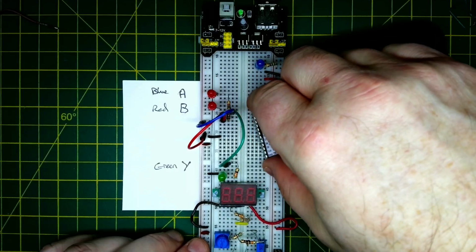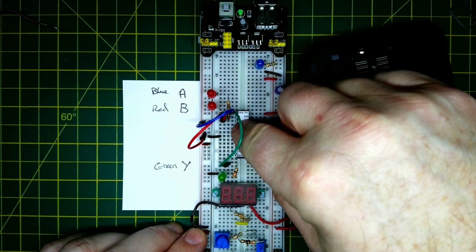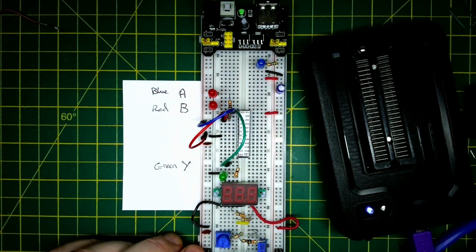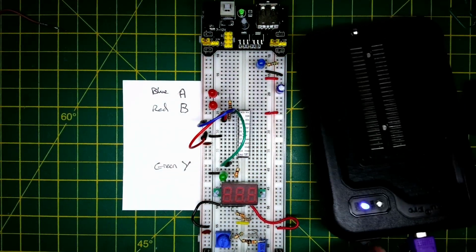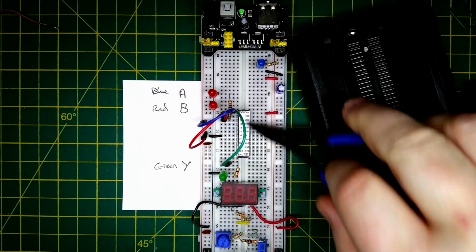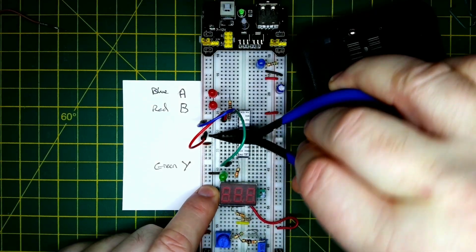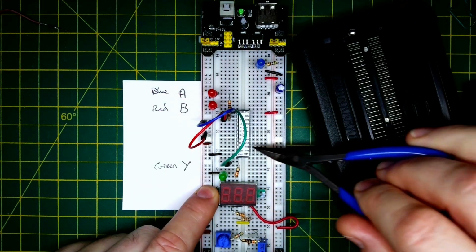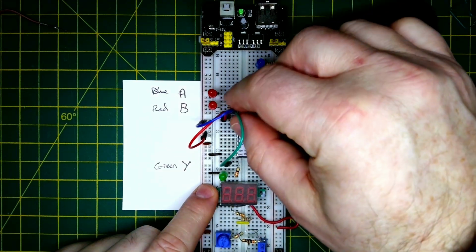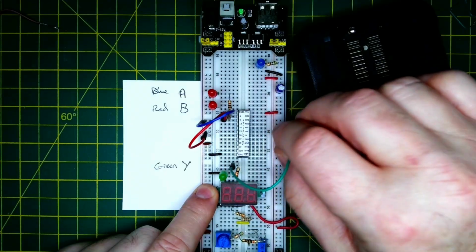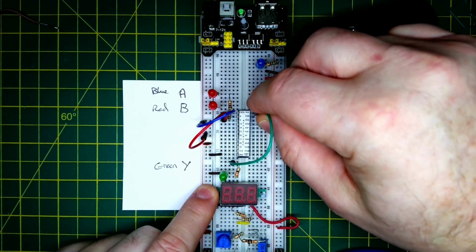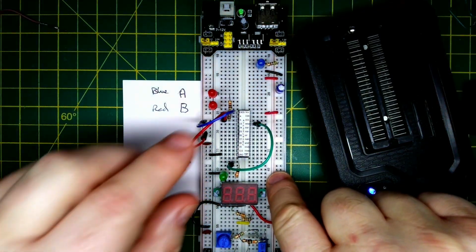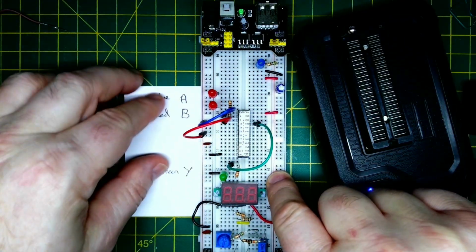Again, A and B are actually offset slightly, so this VCC is in the right place. We just need to move where our ground is. So you'll see that these chips are a fair bit longer. They're 24 pins. And one of the reasons why you might use one of the 16V10s is that it's actually a bit shorter. So now the output, rather than being pin 1, we want the exclusive NOR, which is in fact this pin here. And again, the A and B are connected to these two here.